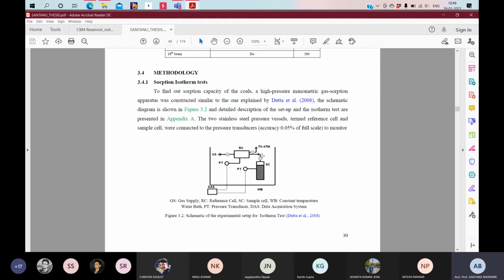So suppose I am going to measure that test at 30 degrees centigrade. I am going to allow the temperature variation only 29.9 or 30.1, not more than that. If it is varying more than this, then there is something wrong. You cannot take the test. You cannot take the reading. And this constant temperature has to be maintained by circulating the water or the oil, so that each area of that water or oil container has the same temperature. So you can visualize what is happening there.